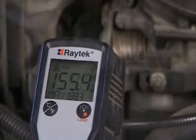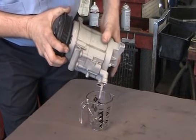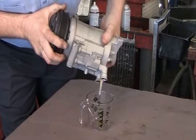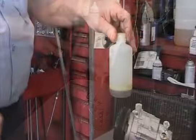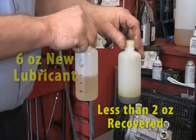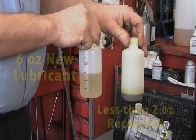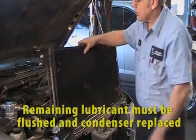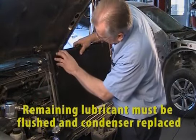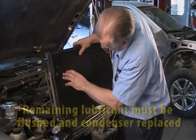Measuring the amount of refrigerant recovered will confirm charge level, but draining the lubricant from the failed compressor is revealing. Not only is the technician likely to find 2 ounces or less of lubricant from the failed compressor, he will also observe the condition of the lubricant in the system. The level of contamination in the lubricant that came out of the compressor will be the same in the lubricant remaining in the system. That 3 to 4 ounces needs flushing, and likely the condenser if the system is a 2000 or newer model.